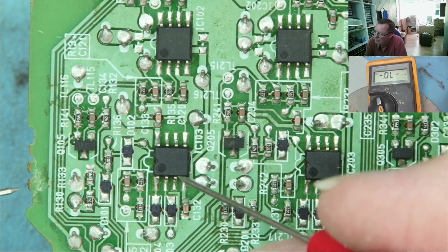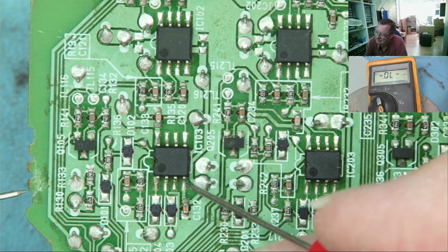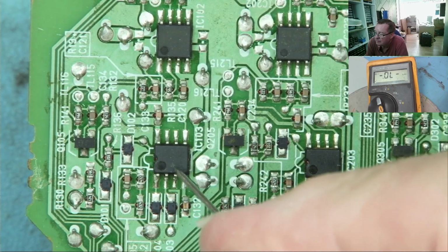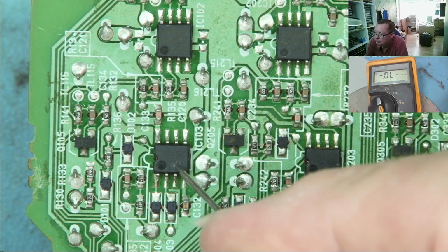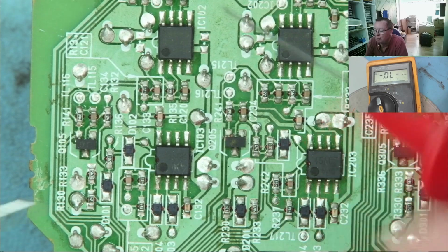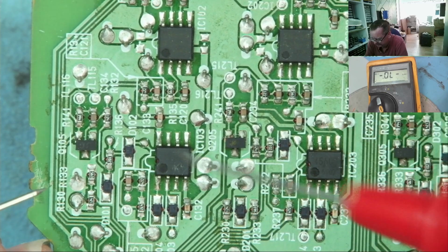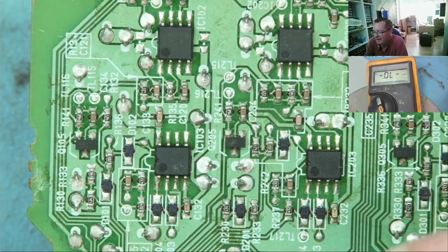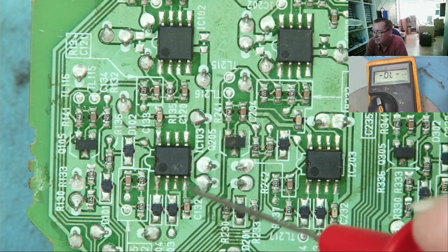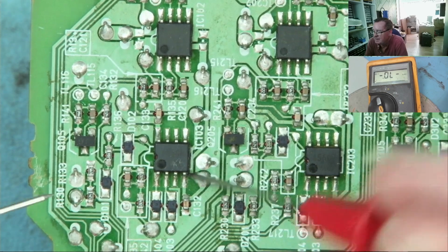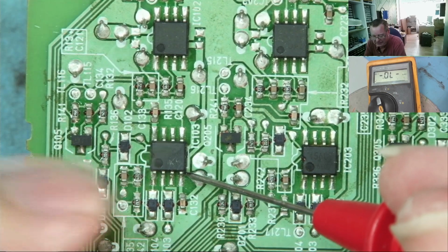Inside here, there will be protection diodes normally connected in a reverse biased direction. So effectively, if you like, the cathode here, I can even sort of scrape it onto the chip, and the anode down to here. And you'll find that on all the inputs and possibly on outputs as well. So normally they're reverse biased. They're just there to effectively guard against reverse voltages. So what we can do is put the positive lead onto the negative supply rail or ground. Now let's have a look at what we see.